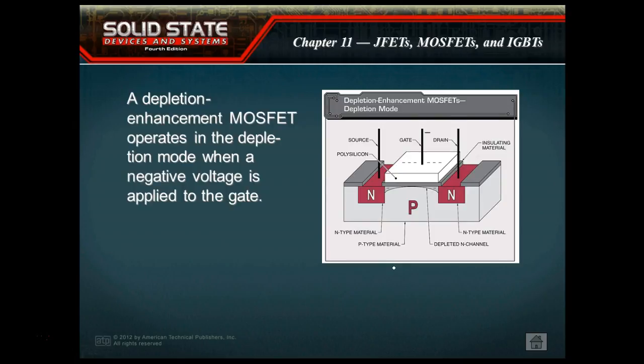But what we end up with, let me find, let's see, I got it on white. So what we do is we come over here, we have the gate, and sometimes it's drawn like this, sometimes it's drawn in the side. And then we come over here and we have our channel. We have the two sides, and then they identify the channel right here. And then normally, if they bring out the substrate, they'll bring this one out. But normally what they do is they come on internally and connect the substrate to the source. And this is usually done internal.